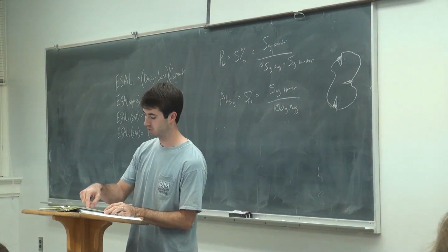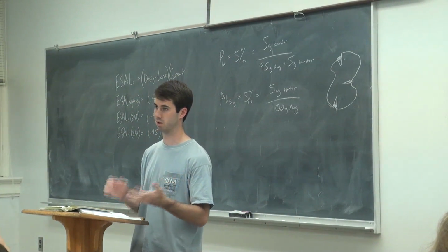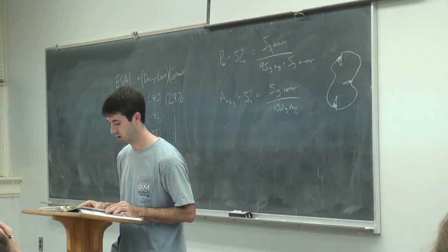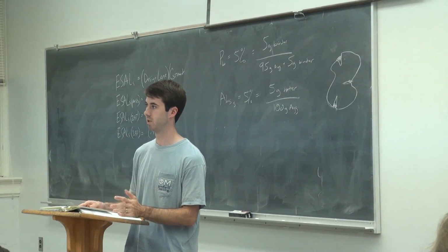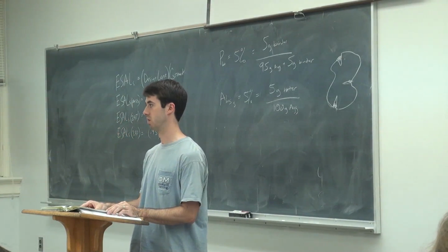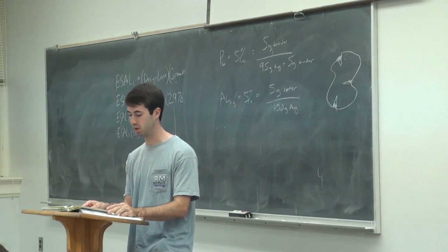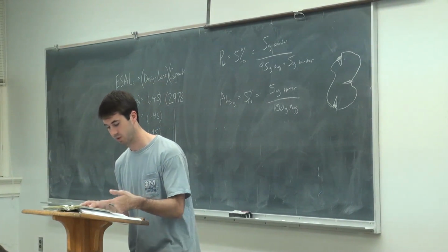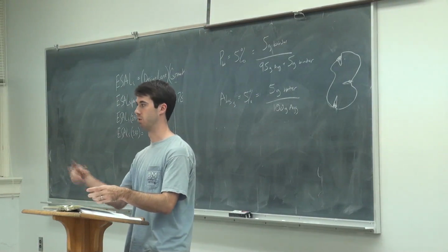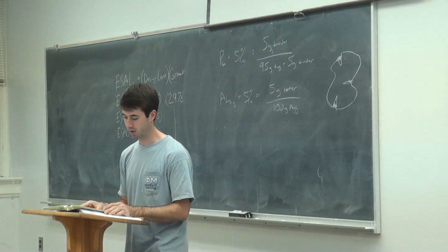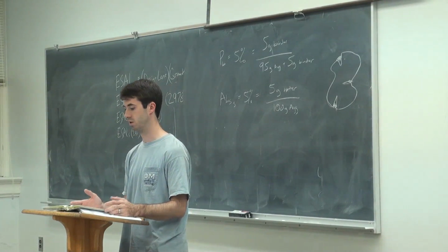So basically what happens is, as you increase the design gyrations, to stay at 4% air voids, you've got to take some binder out because you're compacting it in more dense form. What would taking binder out help with? Rutting. So if you got high traffic and lots of loads and you have less binder, you're less likely to have rutting issues. So that's where that concept comes in. Same thing, as the temperature increases, you increase the number of design gyrations, which effectively means you end up taking more binder out. And you have less issues with rutting, which would be good because you've got a higher design temperature.